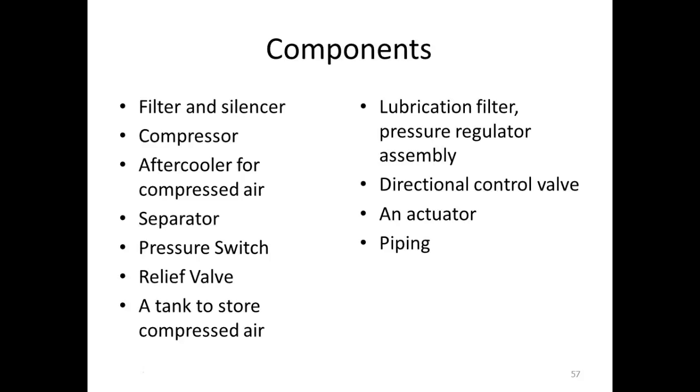It starts to rust on the inside of your tank. When it starts rusting the inside of your tank, then the tank will start losing its strength. And eventually what could happen? It could burst on you. So yeah, I'll go out there about once a month and drain mine at the house.